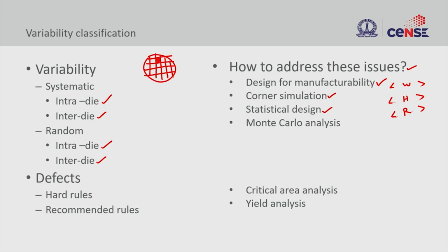So whether my random variation follows a Gaussian spectrum, or this is a completely normal distribution, or undetermined. There are multiple ways to take the data of this random distribution, and then you can model it through Monte Carlo or any other simulation in order to look at how my device performance is going to be affected for all these random and systematic variations.